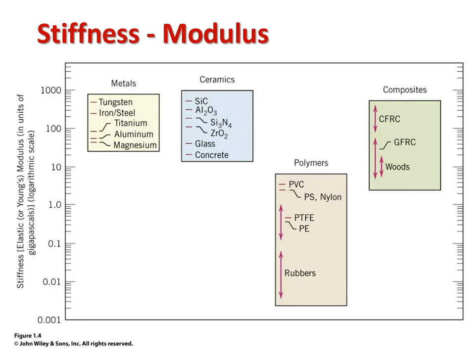Speaking of high end, what's the general range? Much bigger spread than you saw with density, almost 6 orders of magnitude spread. And if you look at polymers, this is where you pay for that light weighting. You've got the better part of 4 or 5 orders of magnitude between your average ferrous alloy and polyethylene, which is much less dense. So, definitely can't have it all unless you go with a composite.